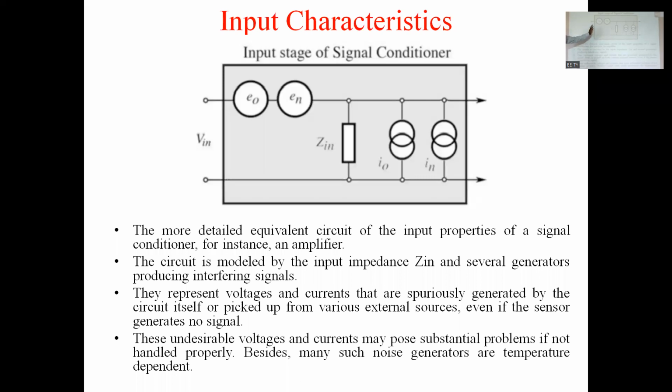Signal conditioner, that means we are interfacing the output of the sensor. Sensor चा output ला represent करतो. So it is having an impedance characteristics किंवा diagram मध्ये impedance Zin आणि Zout. So similarly, V is nothing but input voltage to the interface circuitry. At the same time, Vout is nothing but output voltage of the sensor element or sensing element. Sensing element's output voltage, we are interfacing that.